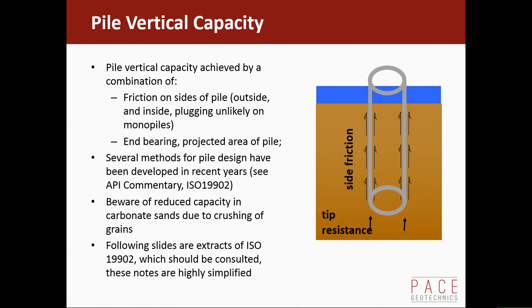Oh, what are we going to do about this? The answer is that what they did was to grout it. In that case, they pump grout, and that gets around the loss of friction due to crushing of the sand grains. When the sand grains crush, you don't get that horizontal stress, which is generating the friction against the pile wall. Well, we know all about this now.